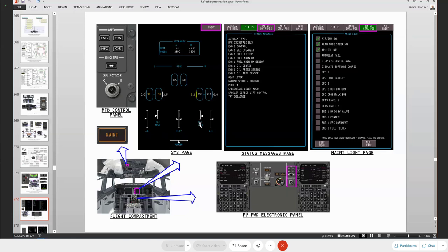The flight spoilers, like I said, the input on your NG is from panels 4 and 9. On the MAX, they're panels 5 and 8. Okay, the reason why they got changed to 5 and 8 is because 5 and 8 have to be functional on the MAX. Okay, you cannot dispatch the airplane if 5 and 8 are disabled. Okay, so since they have to work all the time, it makes sense that those are the inputs for this indication here.